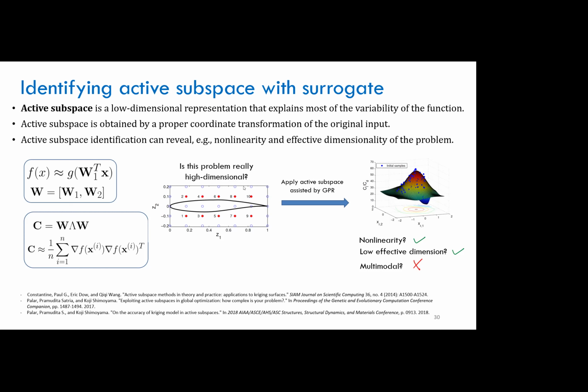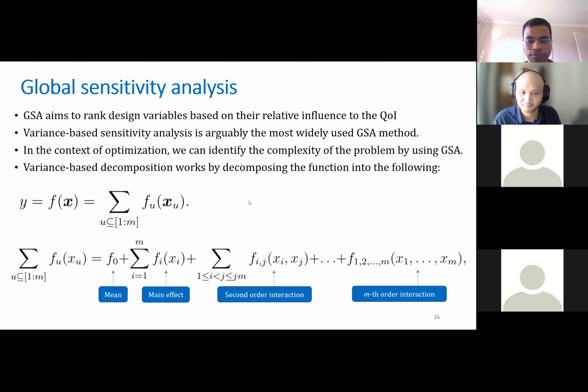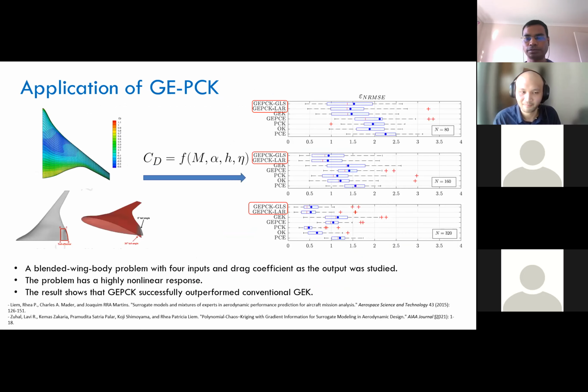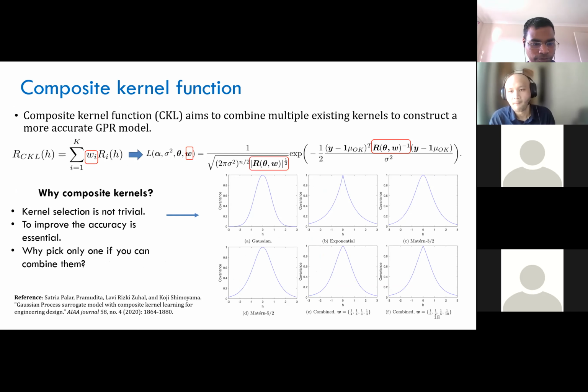Hello. Thank you for your presentation. I just had a question. When you mentioned that you are using a combination of kernel functions on slide 19, I assume that each extra kernel function has another hyperparameter that should be optimized. So you're providing more flexibility for your kernel function, and I think the number of DOE points should at least grow linearly with the number of these hyperparameters. Otherwise, you have the risk of overfitting.